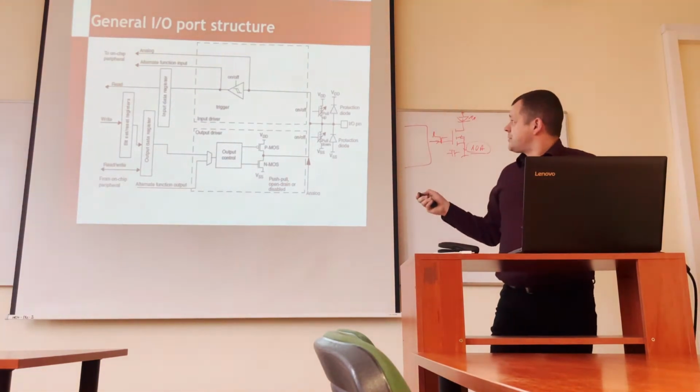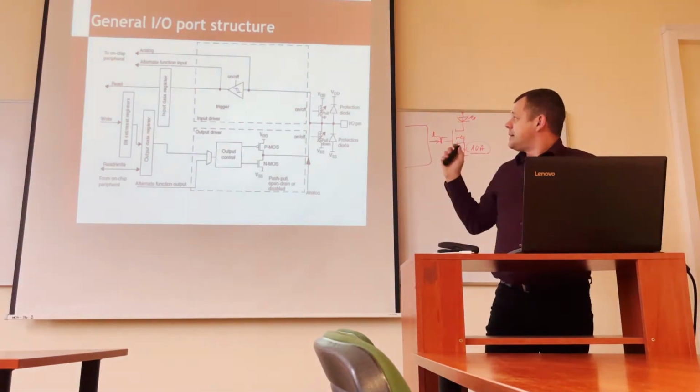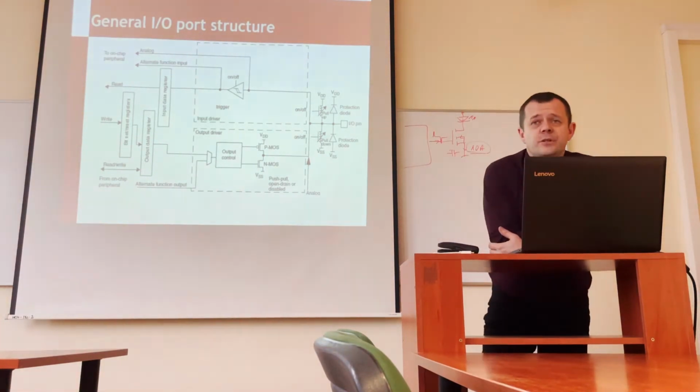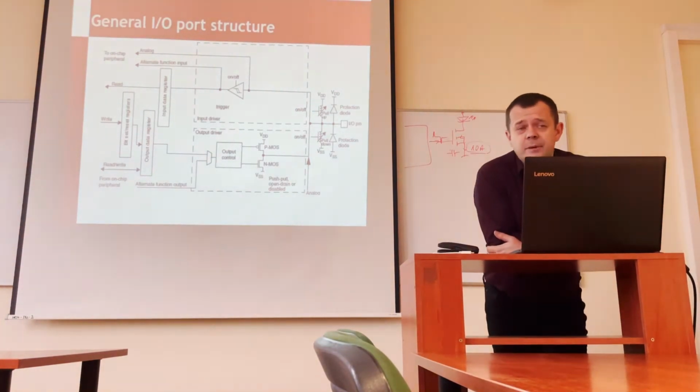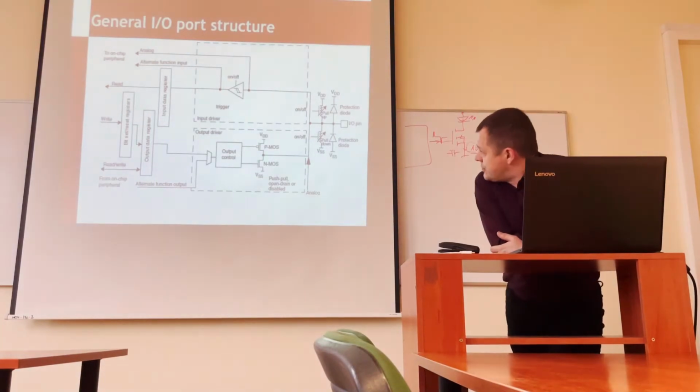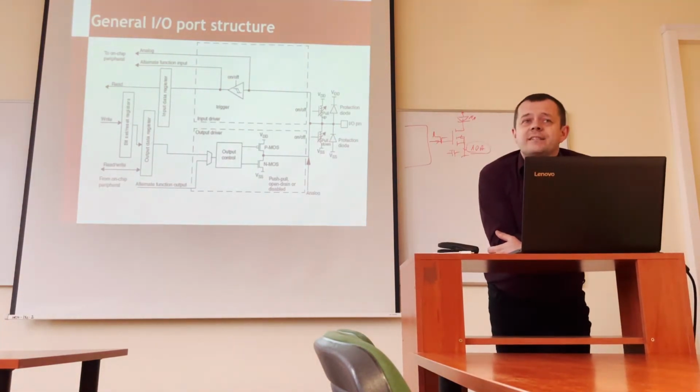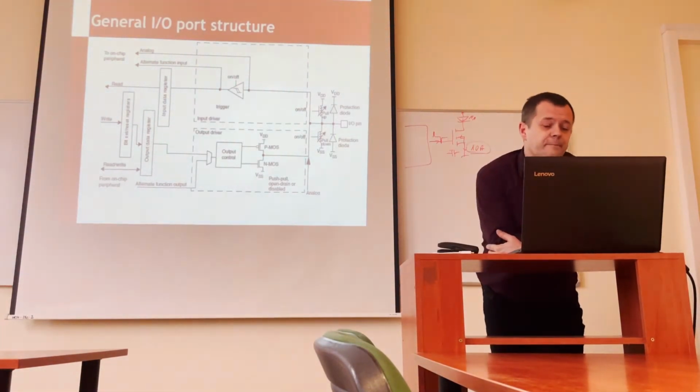For this functionality, we need a pull-up. For open drain functionality, we usually have the pull-up externally, but in some applications, the internal pull-up makes it work.